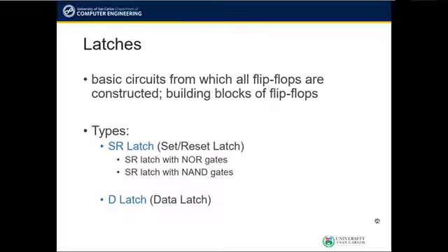Let us now discuss latches. Latches, as mentioned earlier, are also storage or memory elements. They are considered the building blocks of flip-flops. There are generally two types of latches. The SR latch, which can be implemented using NOR gates or NAND gates, and we also have the D latch. Let us now discuss how these latches are constructed and implemented.